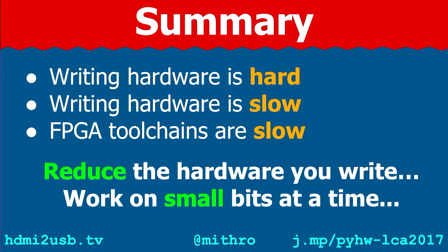So in summary, writing hardware is hard. It's also very slow, and FPGA toolchains are slow. So what we want to do when developing hardware so that we can iterate quicker is reduce the amount of hardware we write, full stop, and work on small bits at a time. And these two things are why Python and MiGen and MiSoC and LiteX are so powerful and able to do so much with so little resources.